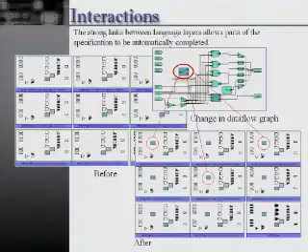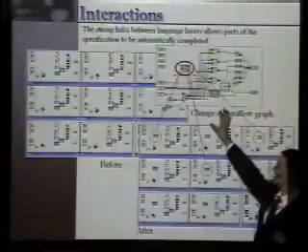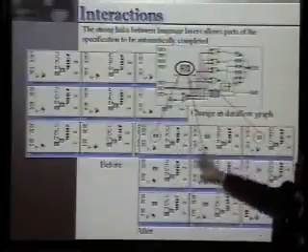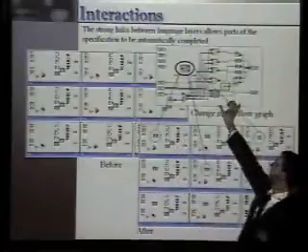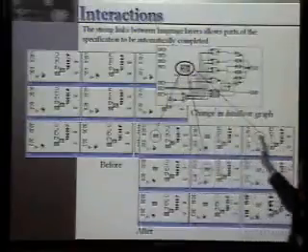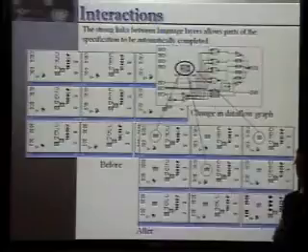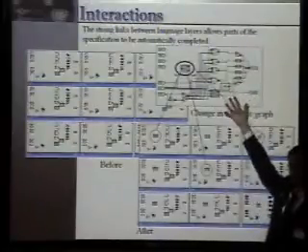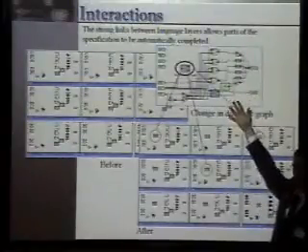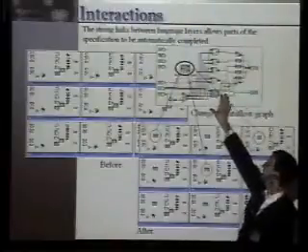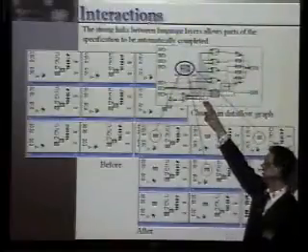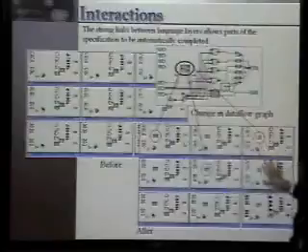On top of this, again, is a tool that watches your actions as you build the data flow graph and modifies all of the modes that you've previously created. So this one, again, is a 1-bit ALU. Each of these modes says for a particular opcode what ALU response do you want, and it tells you how to reconfigure this underlying graph to accomplish that response. If you make any modifications here, let's say you add a new component, all of your actions are monitored and reflected through this whole data flow graph, so that link is correctly maintained.